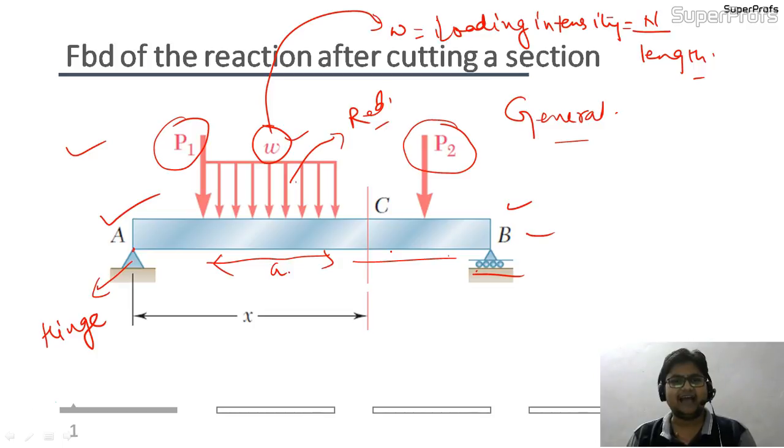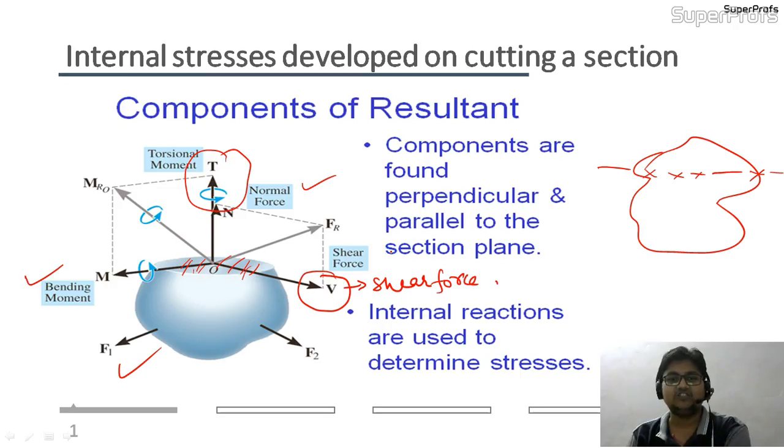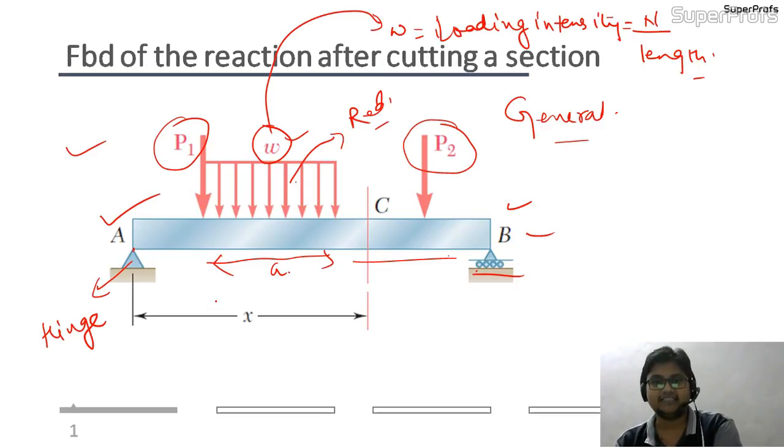So I will be taking section at 2 points, and I will show you how the internal forces are coming into picture. As from the last slide, you just saw how an arbitrary body, if it is cut and it was loaded earlier, these were the internal forces that I showed you. So in the same manner, I will be taking two different sections, and I will show you how the internal forces are being developed in the two sections.